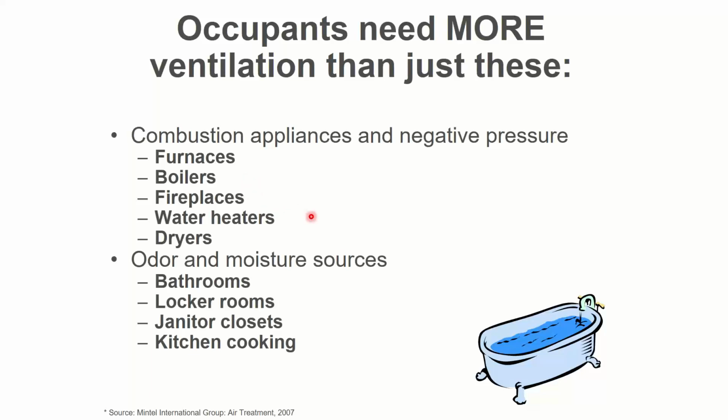But then as boilers get bigger and the boiler room gets bigger, now you have to put combustion louvers in the wall to open up whenever the boiler's on, to be able to suck enough outside air in. Or you have to go to direct vented appliances. So anytime you have combustion going on, you need a pathway for air to get into the building, into the area of the mechanical equipment, in order for it to use that air for combustion and exhaust it out. That is not part of the ventilation air we're talking about.